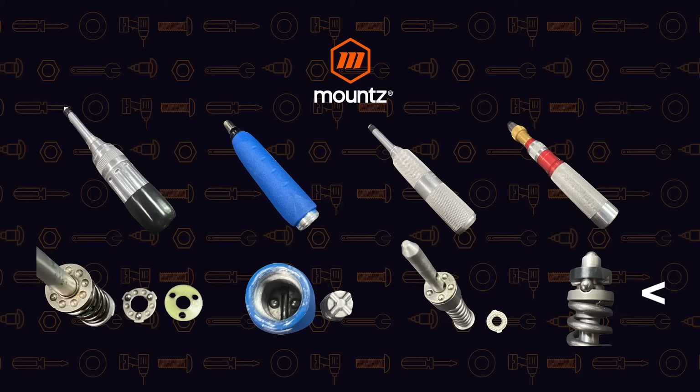And so when we take a look at the Mountz mechanism, it uses a different type of clutch than what would be with all of these styles. It's more of a ball clutch type of application, and we use a radial cam mechanism in our torque drivers.